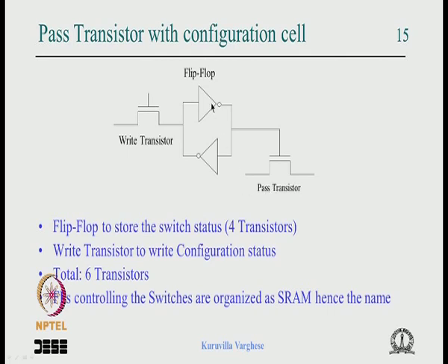Important thing to remember is that the flip-flop is made of 2 inverters, and one inverter is made of 2 transistors, one NMOS and one PMOS, PMOS to the VDD, NMOS to the ground. So this inverter is composed of 2 transistors, this 2 and this one, that is 2 plus 2, 5 and 6, and this can sometimes be a right transistor with isolation, can be big. So one switch means 6 transistors. Okay, so you can imagine it occupies quite a lot of area.